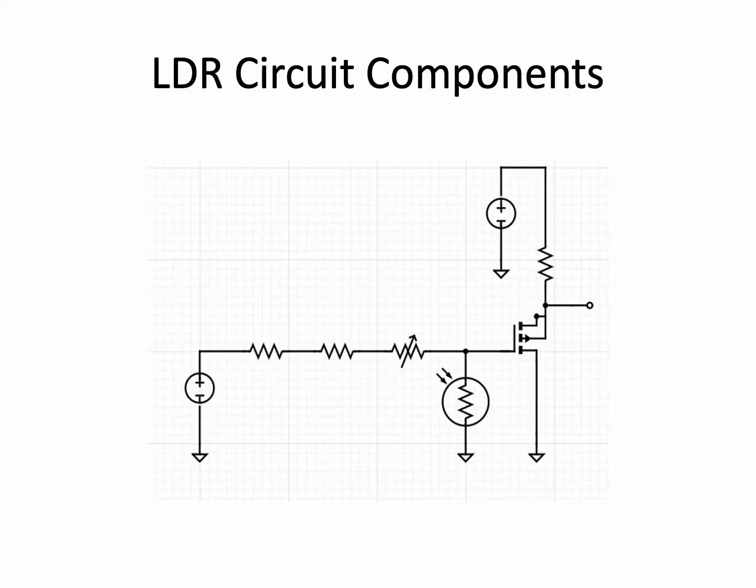The LDR, or light-dependent resistor circuit, is a critical component in the Beat Laser design. The LDR circuit indicates to the Raspberry Pi when one of the 8 laser beams is broken by the player. Because the Pi only has digital I/O, this is accomplished by switching the voltage on an input pin on the Pi between 3.3 and 0 volts using a 2N7000 MOSFET.